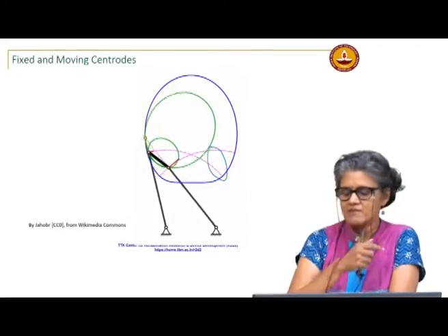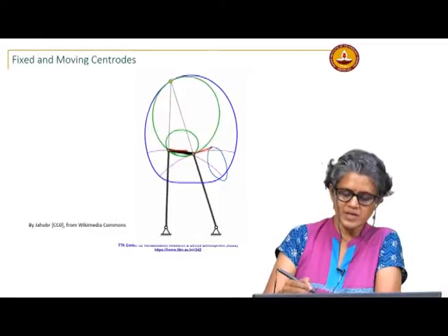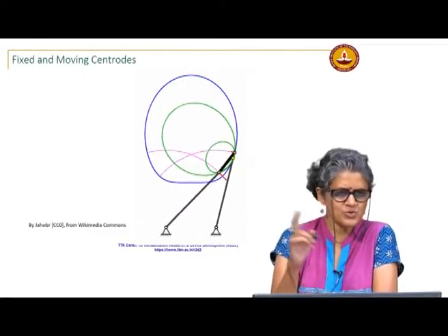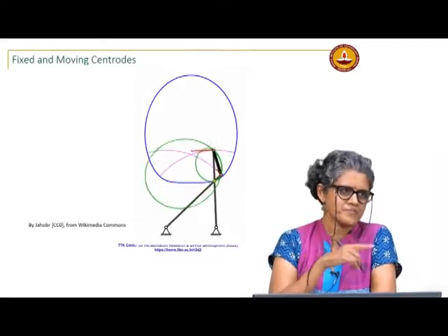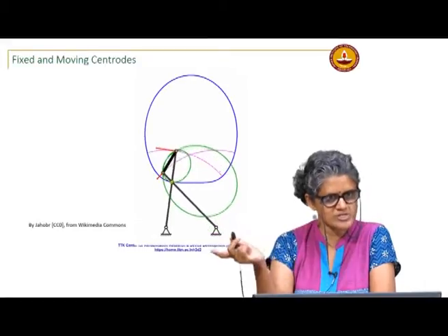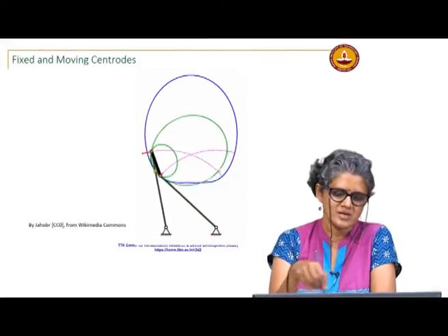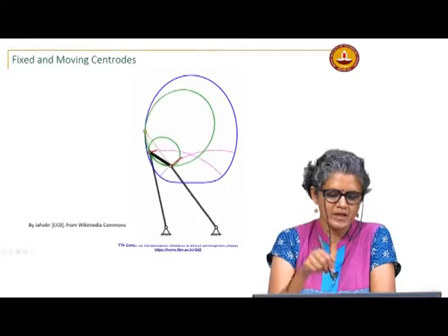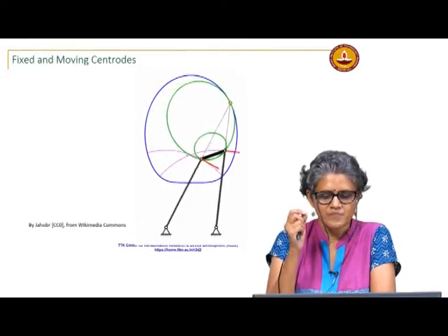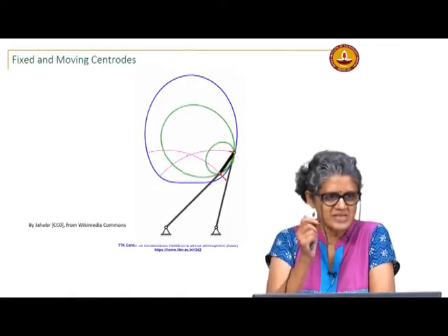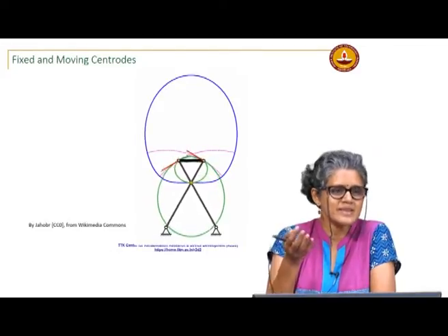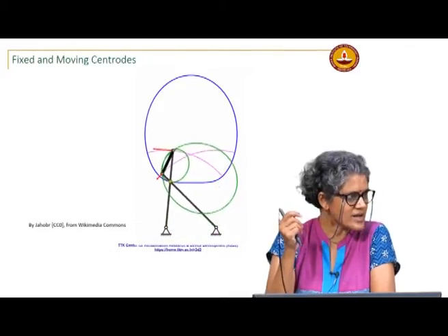Okay. But I need to do some reading on that to check. For these two points, you do have reversal of motion, even with the crank rocker. If you look at it, the velocity goes to 0, then it reverses. So, that is what the coincident points are in this case, but we do not really treat those two pivots as coupler points, because you are not going to get anything more interesting than a circular arc.